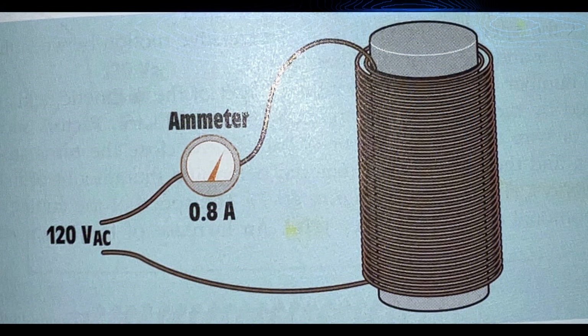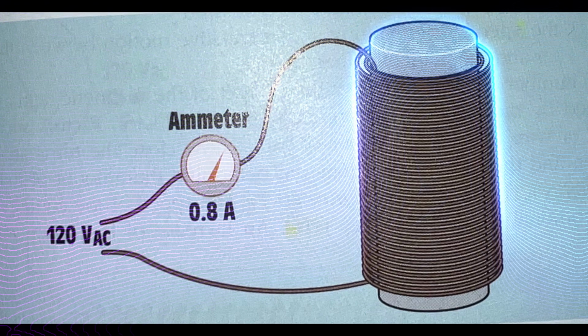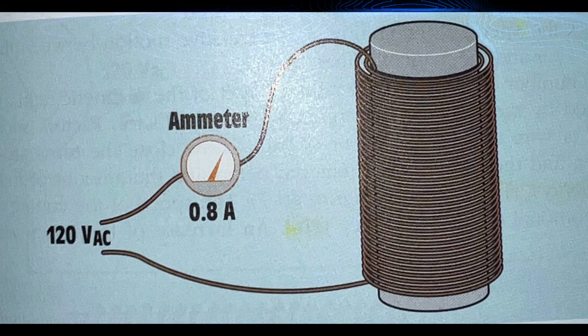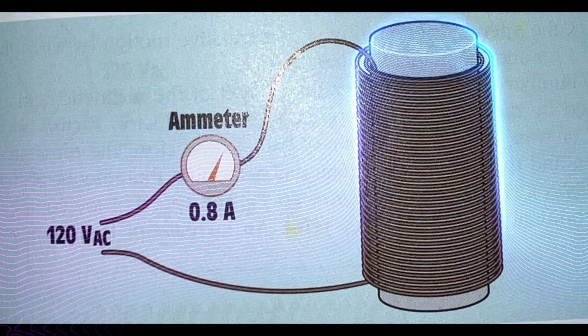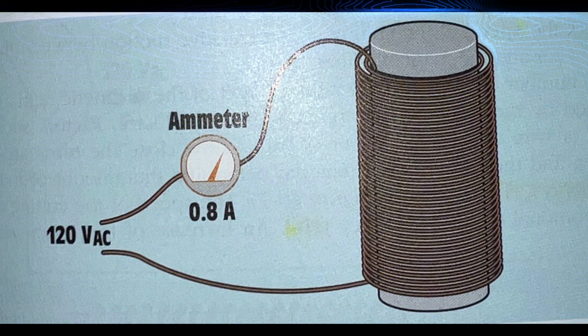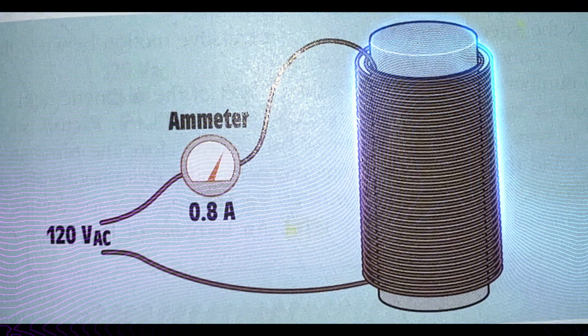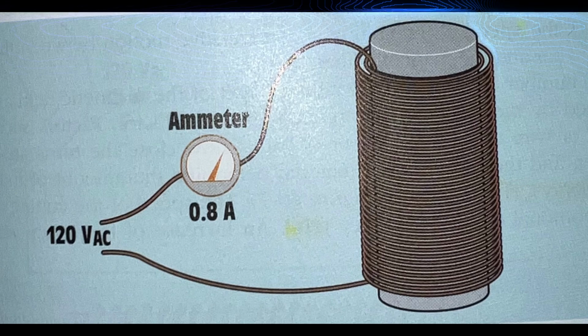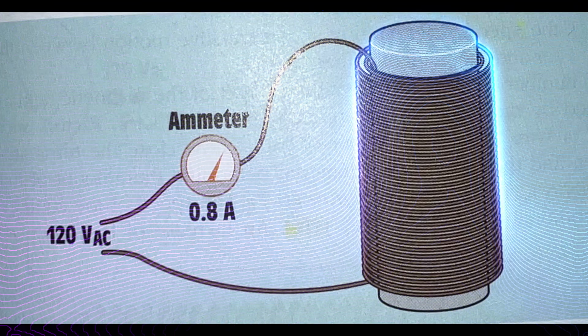VARs can be computed in the same way as watts, except that inductive values are substituted for resistive values in the formula. VARs is equal to the amount of current flowing through an inductive circuit times the voltage applied to the inductive part of the circuit.